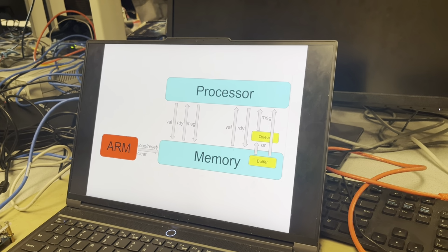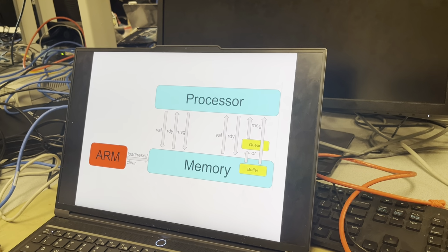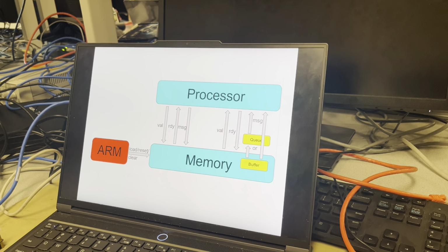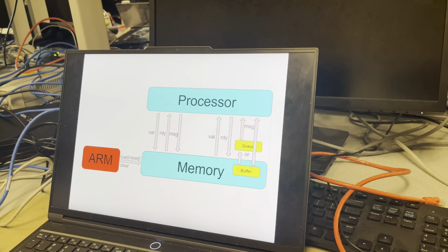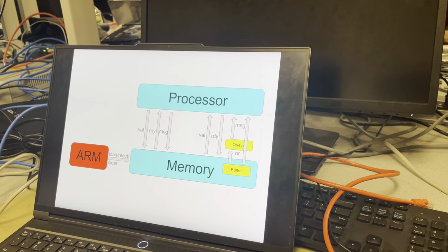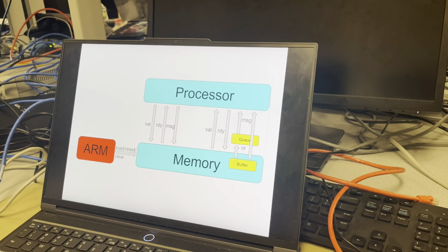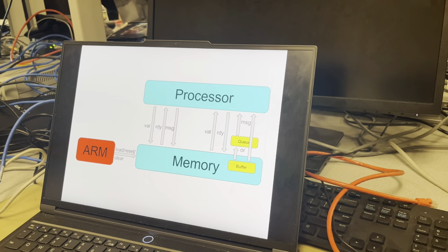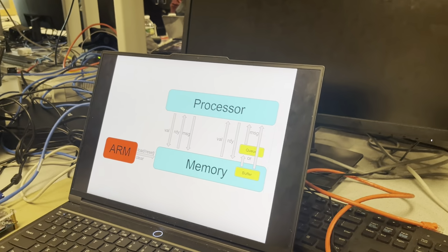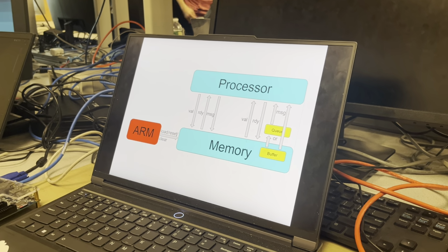In this memory, we use the shared memory, which can be read and written from the ARM processor and the FPGA part at the same time. We also use the ARM to load the initial data from some machine code to the memory. And we also send the clock, reset, and these control signals from our processor to the FPGA part.